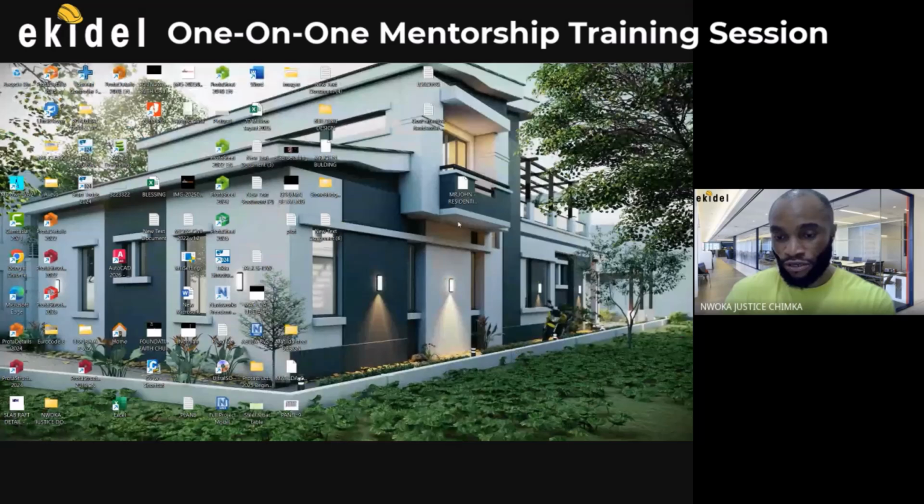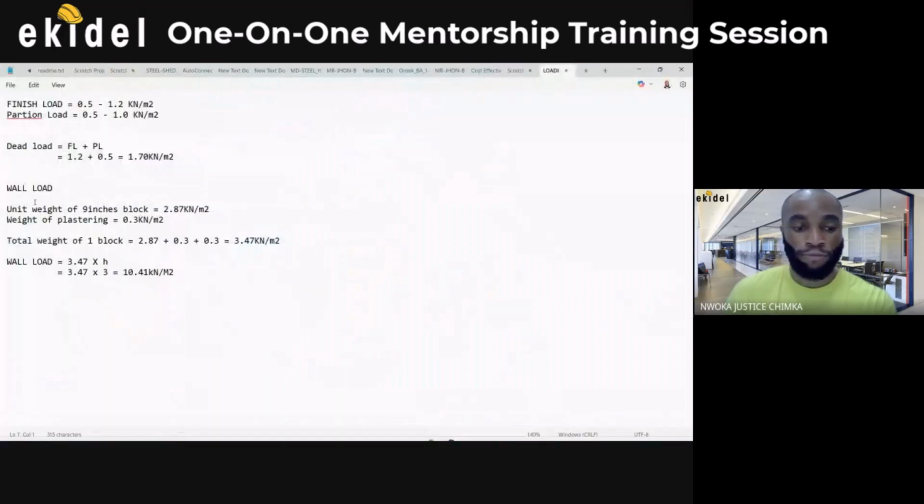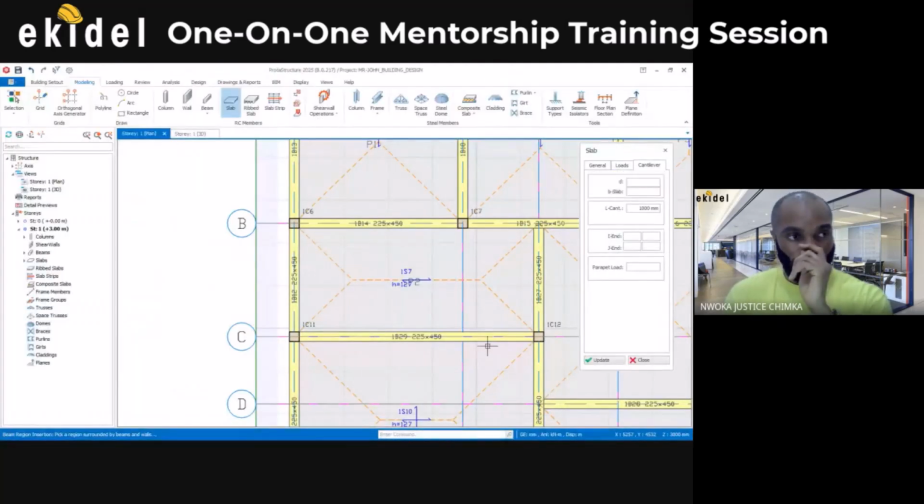For example, you can see this one here is a cantilever. Let me assume that there's a block sitting there. All you need to do is calculate the load of the block. For example, you can see here the block wall load for a 9 inches block wall. Then you can see the total load here if you add plastering and everything. So you just add the cantilever load. If it's a handrail, and the rail is tubular pipes that don't have much weight, you can use 3.5 or even 1.5, if it's not that tall.